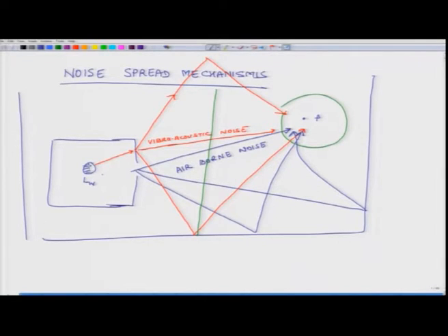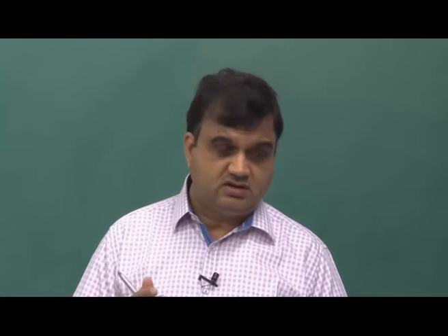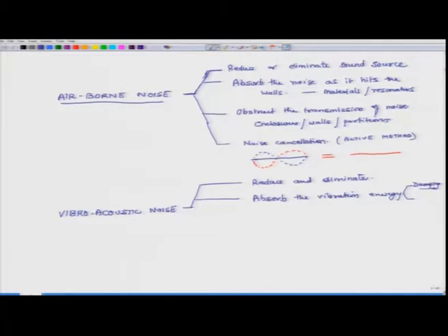Metals in contrast have very little damping, so they tend to vibrate at higher amplitudes at their resonance points. But plastics and other non-metallic objects have higher damping characteristics, so even if their resonance point was the same, they will vibrate at a far lesser amplitude. That is what I imply by damping.